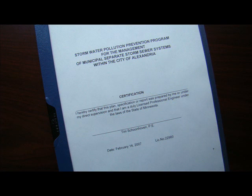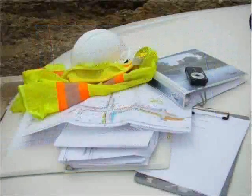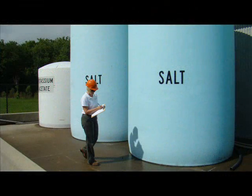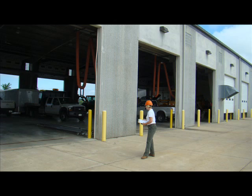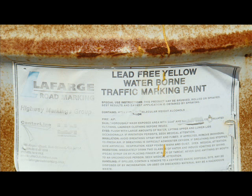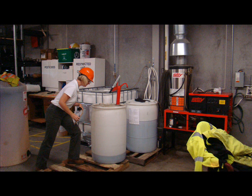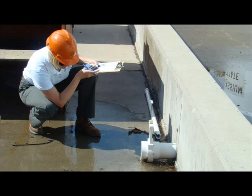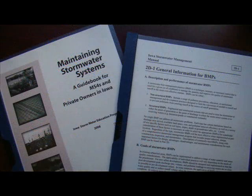The inspection process consists of first reviewing any existing pollution prevention plans for the facility if they are available. Obtain a map for walking around each facility associated with public works operations. This may consist of salt storage, fleet maintenance, signs, painting, chemical storage, airports, and cemetery areas. Identify existing problems and look for potential problems. Determine if best management practices are being implemented and if they are adequate.